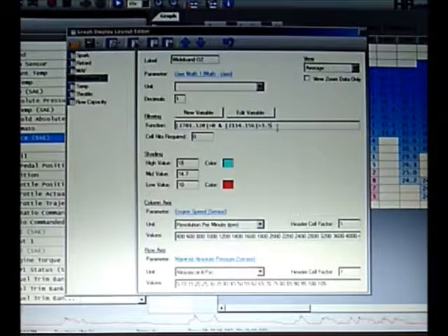Even if you have your foot on the pedal like 5%, it's enough to keep the computer thinking that it's in acceleration mode, and it will continue to behave in a linear way where the output is predictable and proportional to what you're applying as a driver, the amount of throttle that you're applying, for example. So pretty much there's a linear range that goes from like 5% throttle all the way up to 100. And that's the data that you want. You don't want this deceleration data.